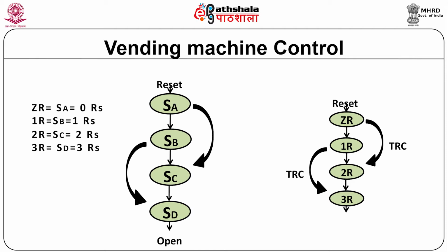The state diagrams make it easy to develop and understand the functionality of the application that uses a state machine. The figure below is an example of a state diagram for a simple vending machine. The oval represents the states and arrows represent the possible transitions between the states.